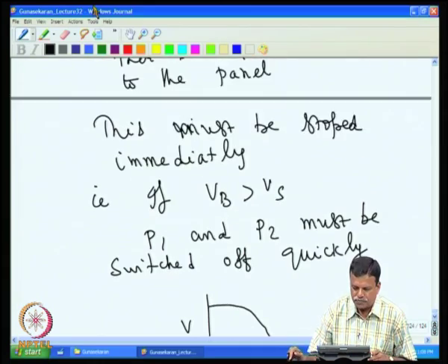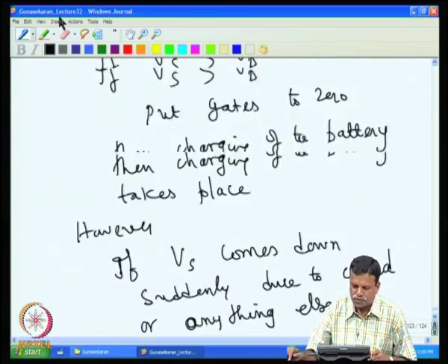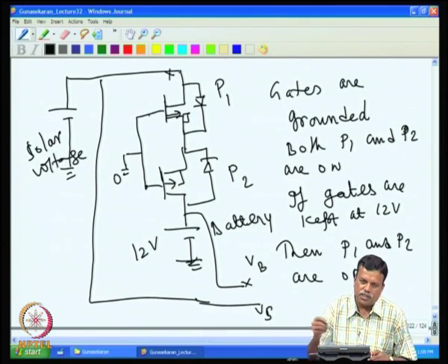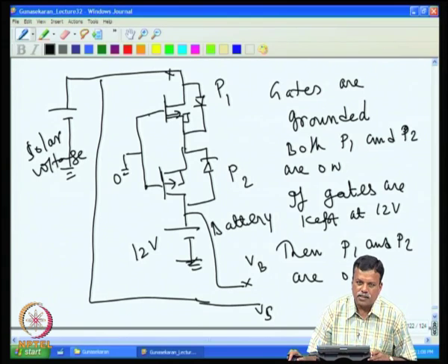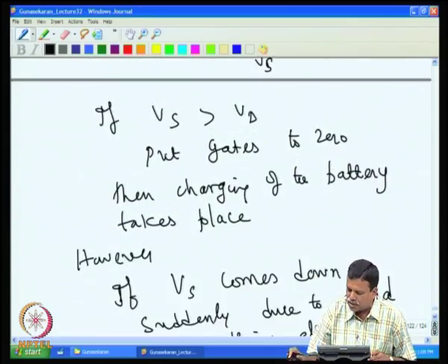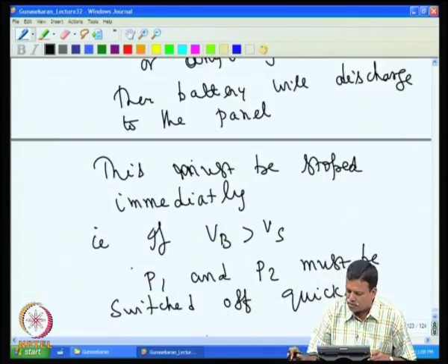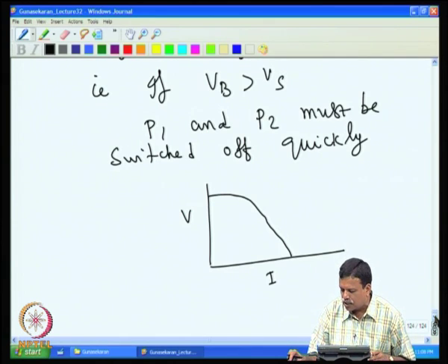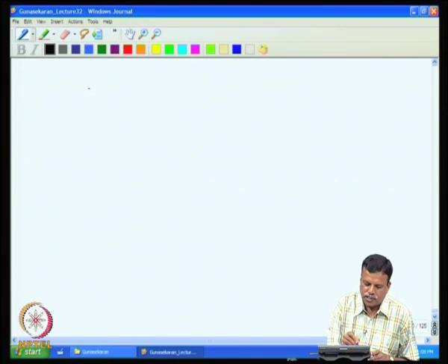And in addition, if battery voltage and panel voltage are very close, it is not easy to detect accurately when the solar voltage has gone high or low, because, for example, in a 10-bit converter, one LSB value can be calculated in the following manner.